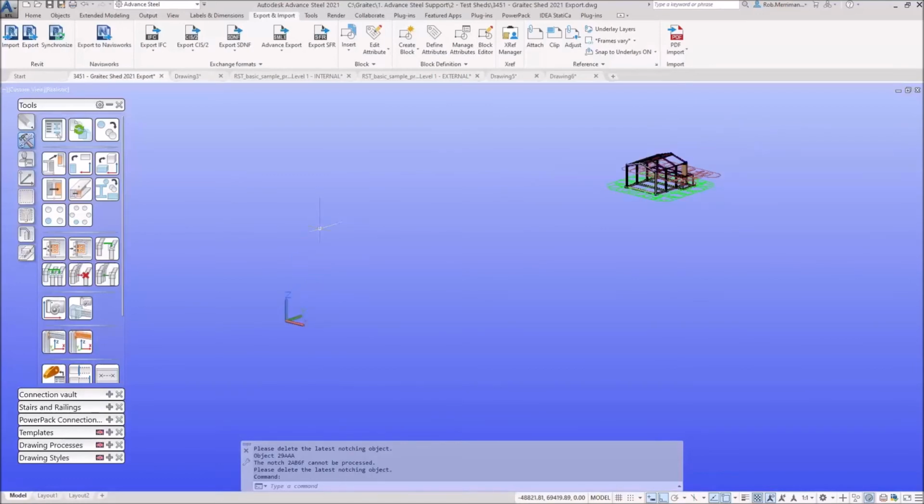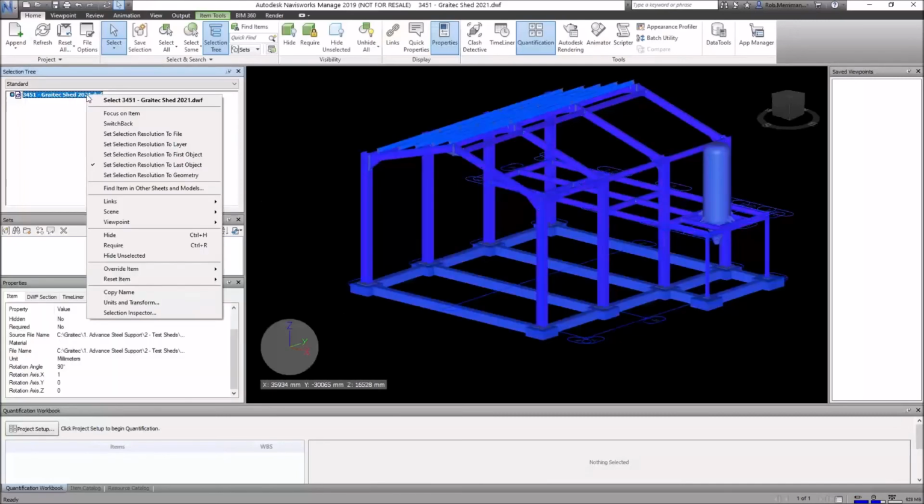When we did the export, it actually messed up the export of the beams, and the bolts came out as just really blocky and really horrible. So you do have to be a little bit careful with it. But if someone's asking me to export to specific coordinates, I would always save a copy and do it in the copy. My Navisworks has come back.